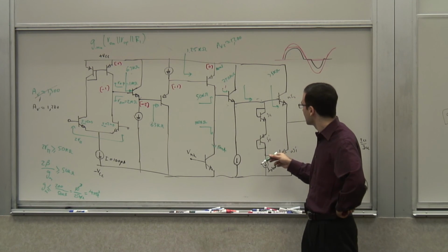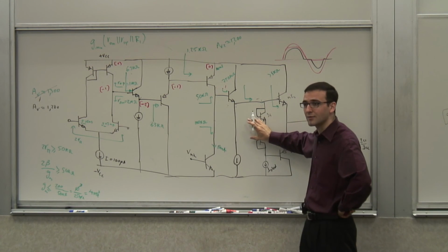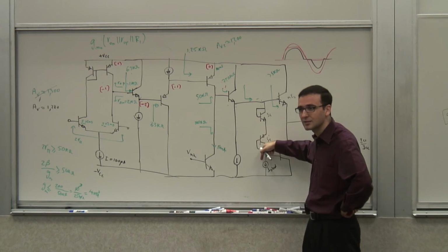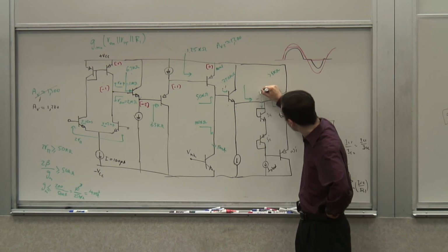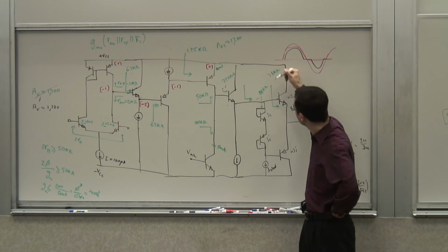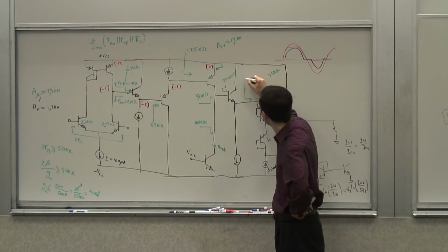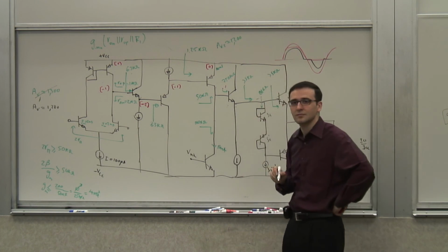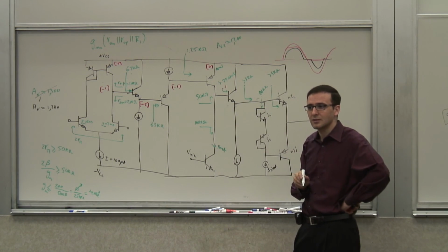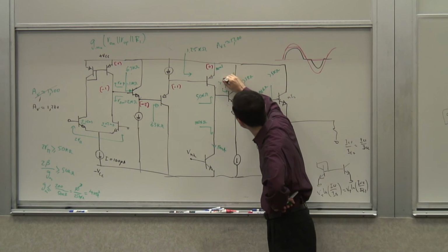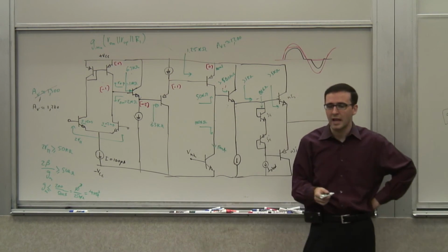so it's, I'm sorry, 100.05 kiloohms. So it's practically the output resistance of this guy, right? Because it's 25 and 25 over 100 kiloohms. So this is 100 kiloohms. This is more than 5 kiloohms. So it's still fair to say this is greater than 5 kiloohms. And if that's greater than 5 kiloohms, it's going to be greater than 750. Oh no, I'm sorry. Now it's going to be greater than 500 kiloohms, which is still okay because then these guys are okay. How about the negative swing?